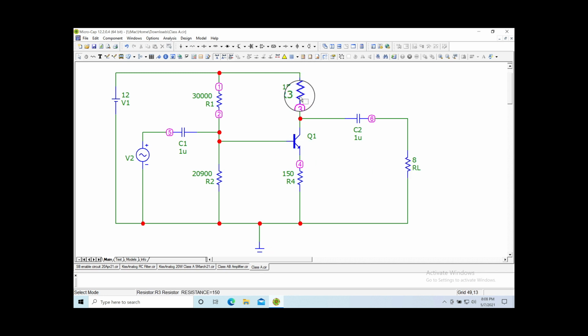Now, the other thing is another parallel path. This 8 ohm load, AC wise, looks like it's shorting out this, because we have a 150 ohm resistor here, and that's a lot lower. Normally, you want your source impedance, where your power is coming from, to be very low, like 12 volts. You want this source impedance over here very low, so there's no voltage drop between this and these components. Same thing here. When you're pulling this down, it's called loading your circuit down.